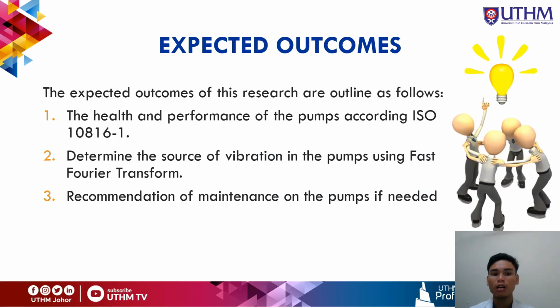So the expected outcomes for this research are, first, the health and performance of the pumps according to ISO 10816-1. The second is to determine the source of vibration in the pumps using the fast Fourier transform method. From this method, we will detect the fault in the pump with the characteristics that are generated from the fast Fourier transform. And the third is the recommendation that can be proposed to the UTHM biodiesel plant management for the maintenance of the pump if needed.